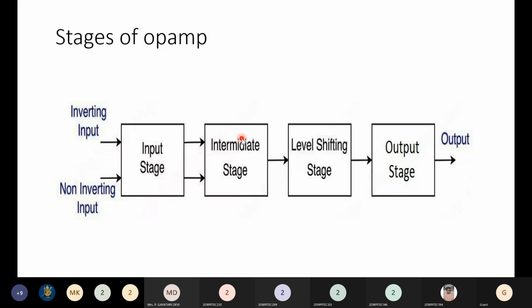Okay, and this small amount of DC voltage will also get amplified in this intermediate stage, because this is a high gain amplifier, is it not? So even a small bias current which is there inside the circuit will get amplified. So along with the AC, the DC will also get amplified here. So what will happen? My AC signal will get shifted by a DC level. Okay, so the original AC signal will get amplified. Along with that, you will be having a DC shift also here.